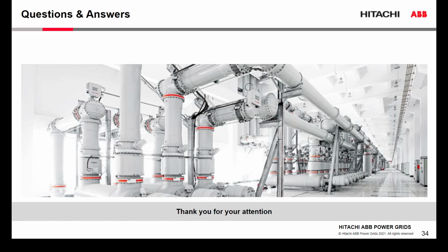Yes. Can you please advise whether the IGA option leads to minimum site installation time, as they come pre-assembled with GIS and the local control cabinet within a housing? As for the IGA installation, the idea is very much to reduce on-site installation time, and depending on the layout and design, we can easily talk about 50, maybe even 80% reduced installation time on site.